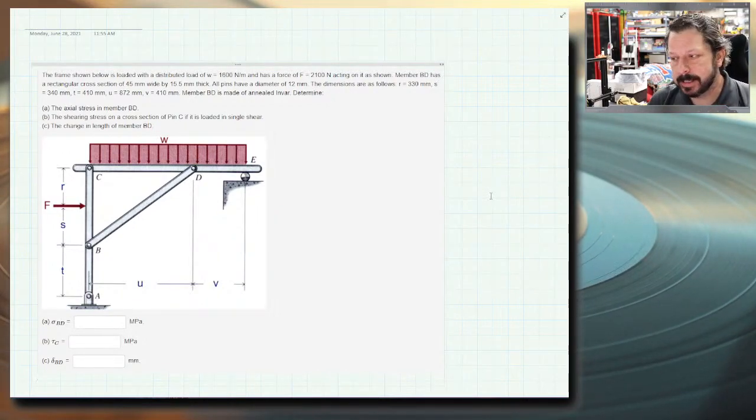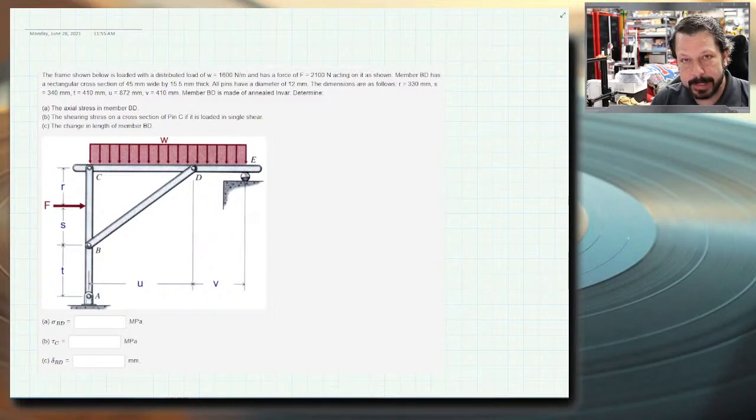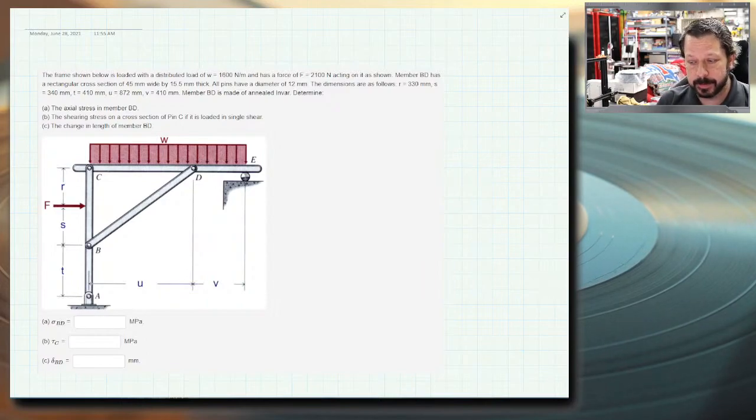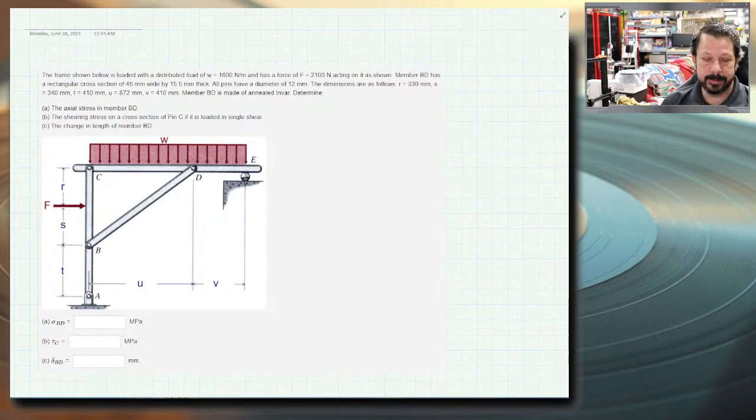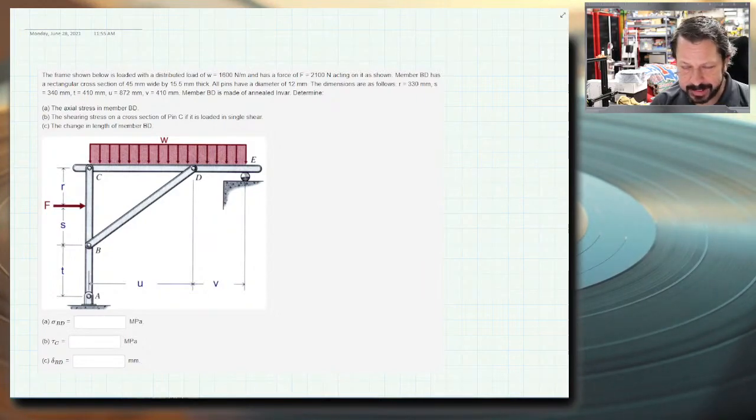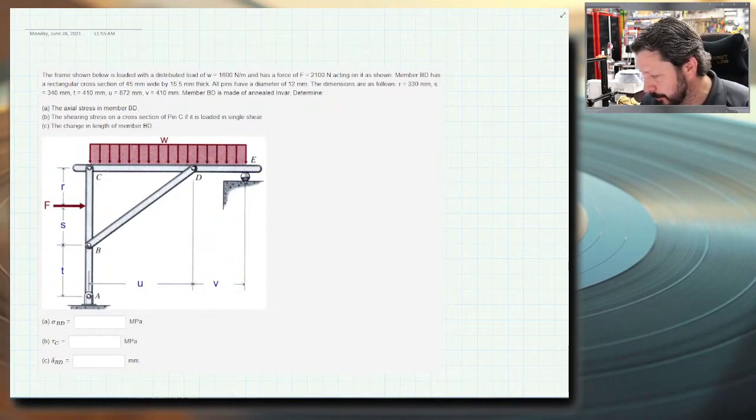Because if it's a machine, you may want to go in and work on taking the pieces apart before trying to solve external reactions. If it's a frame, then you probably do want to find external reactions first. Maybe identify 2 force members if there are any, and then start taking it apart. It's not 100% that you do it that way every time, but that's generally true.